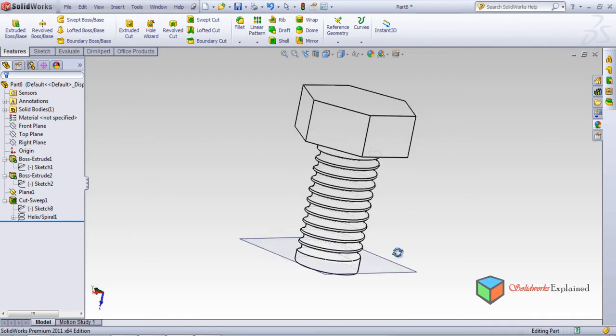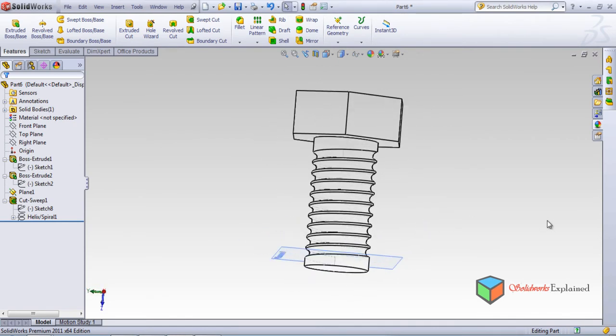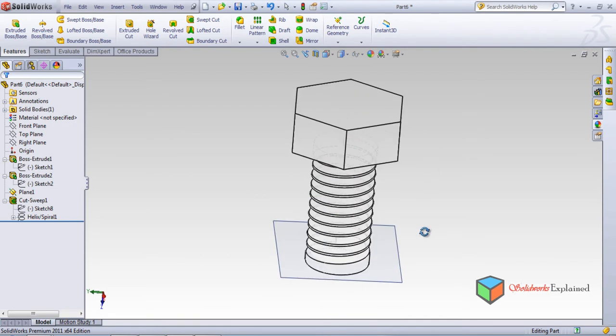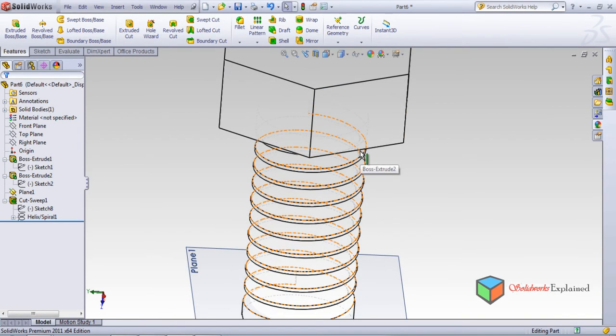Left click. Now here you can see the edges of the part, and plus also you can see the hidden lines. These are dotted lines. Look, the orange dotted lines are called hidden lines, and they represent the parts which I cannot see in the front view.